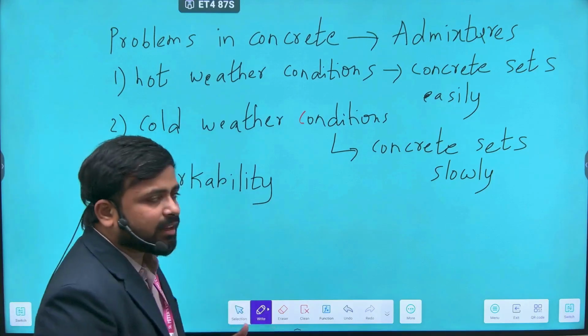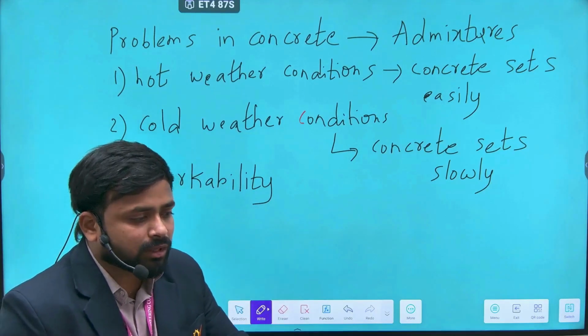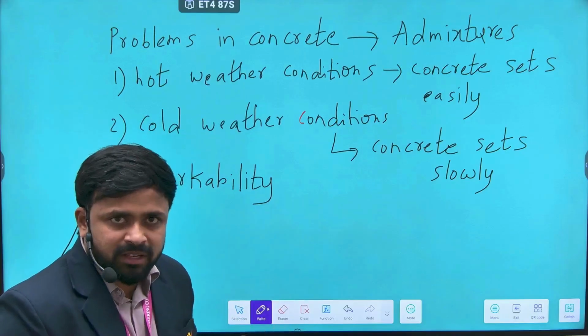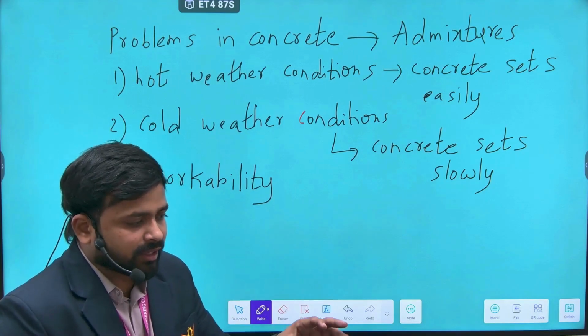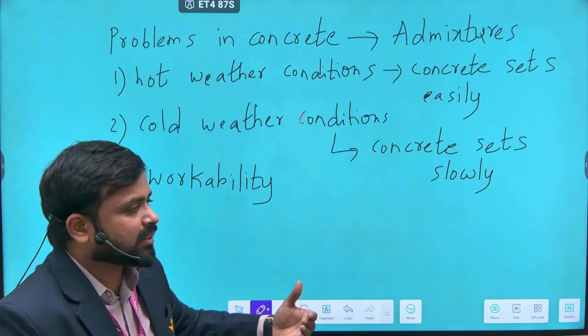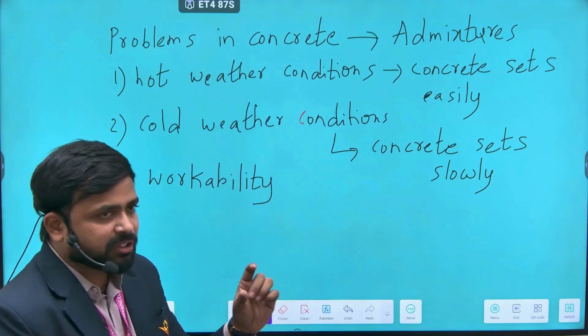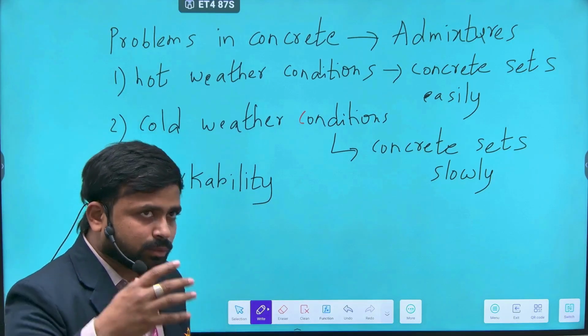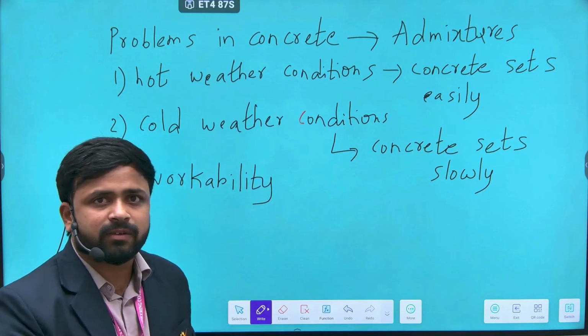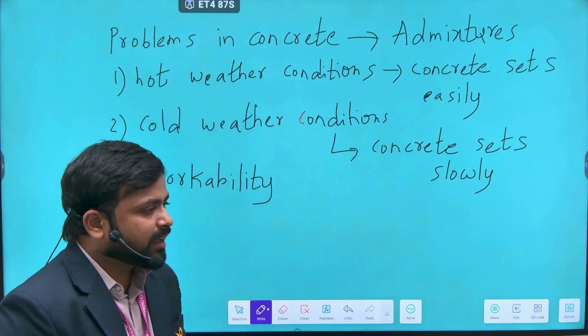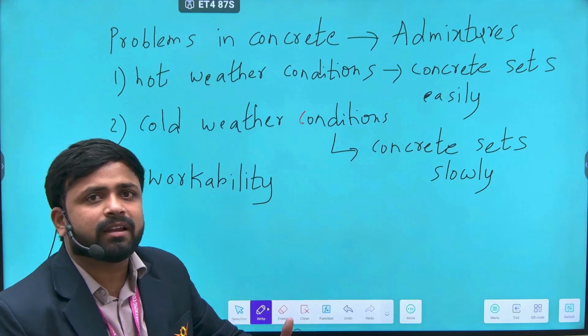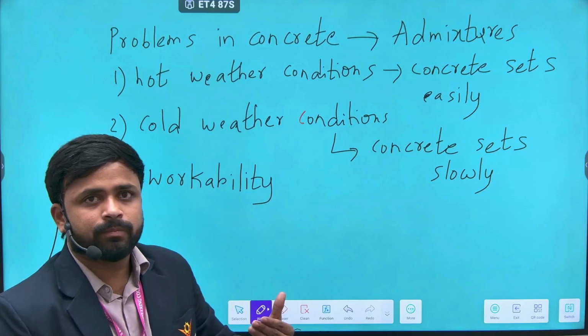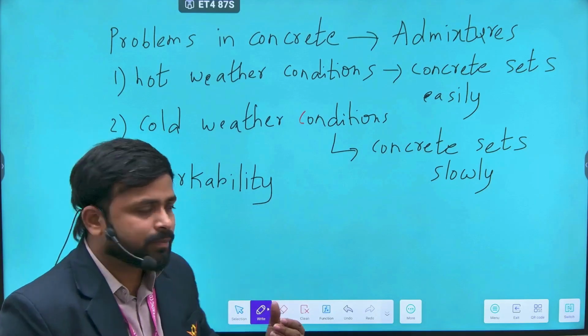If you are adding water to the concrete after construction of the structure, the water which is occupying the volume, due to the temperature conditions, due to the climatic conditions, gets evaporated easily, and on the surface itself the cracks are visible. So it is also the major problem in concretes.